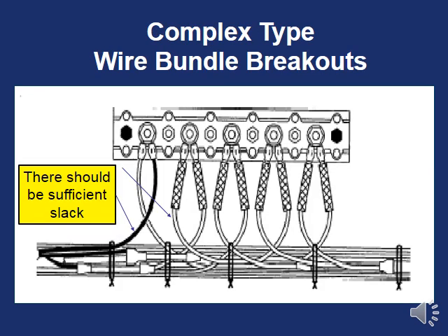This picture emphasizes that there should be sufficient slack when wires are routed from the terminals into their bundles. These should not be super tight. You want to give them enough slack so that there's not strain.